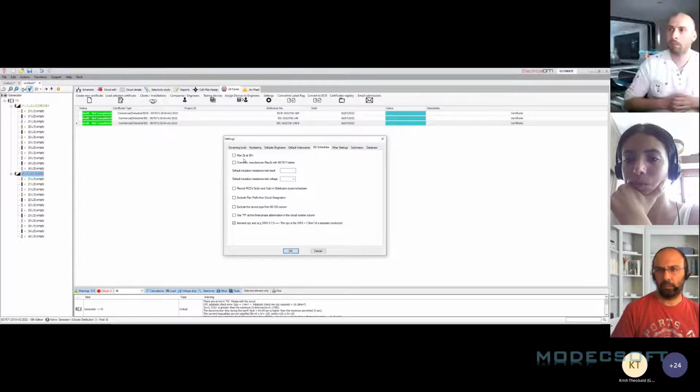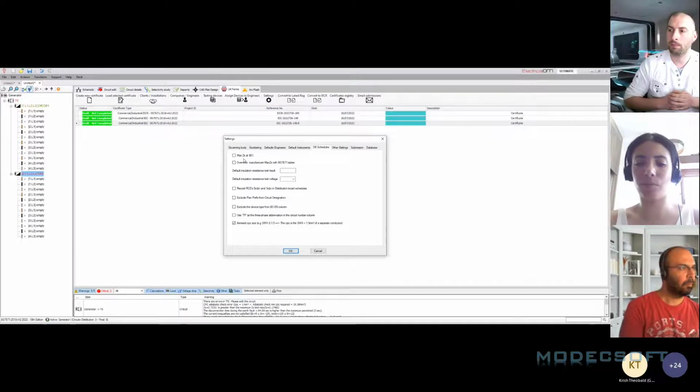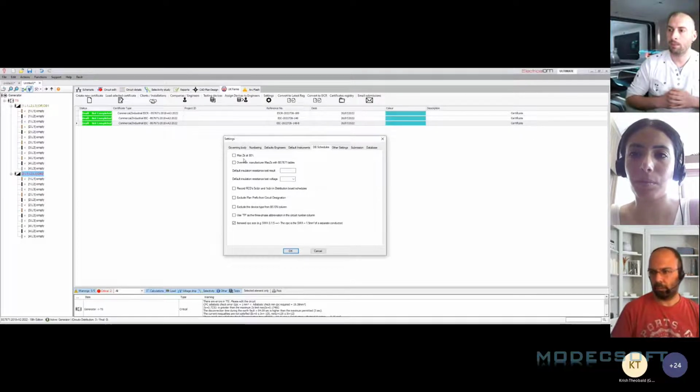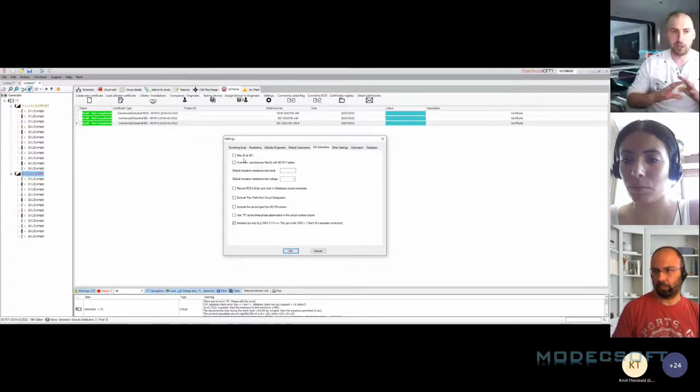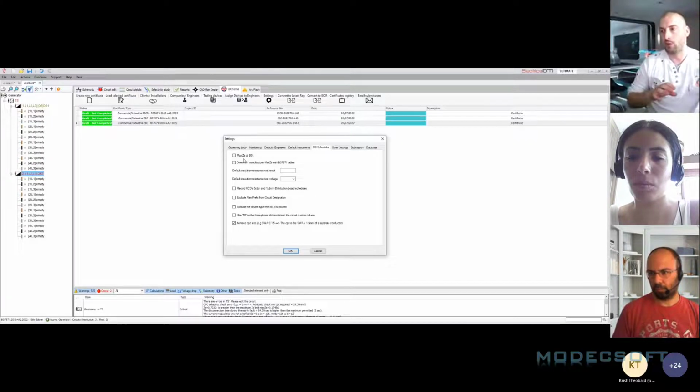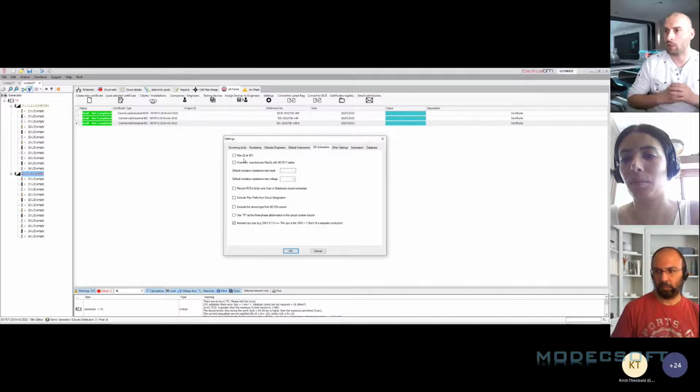So, I understand that was because of the temperature correction, but let's say that I also want to make certain allowances for appliance cables, etc. So there's no option right now for me to set it to, let's say, 75%, right? Well, it's up to you as a designer how you would apply various information, but there's no options within the software other than on the UK forms to flag up an issue where you have ZS values below 80% or above 80% of the maximum ZS.